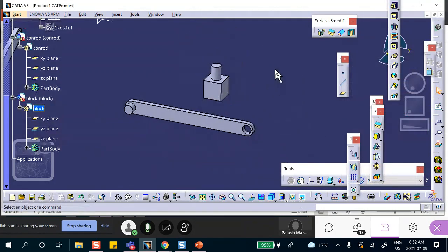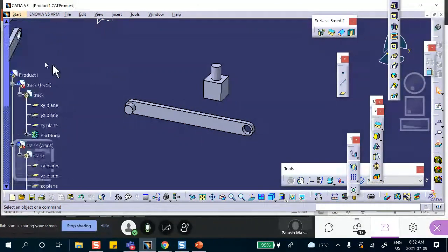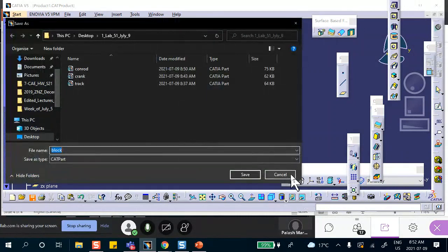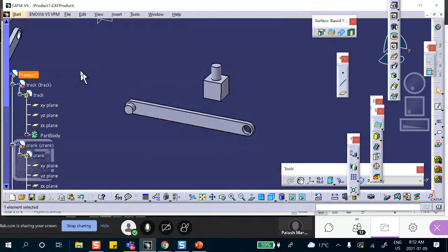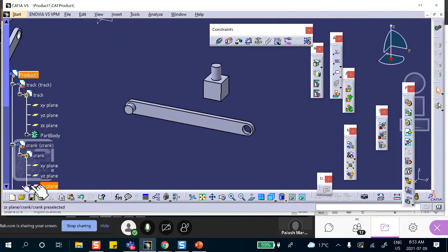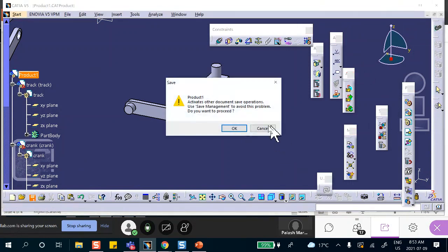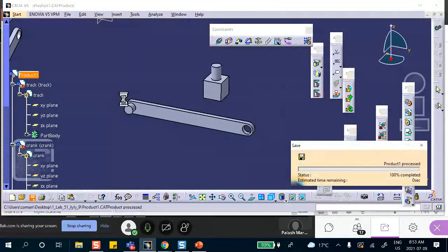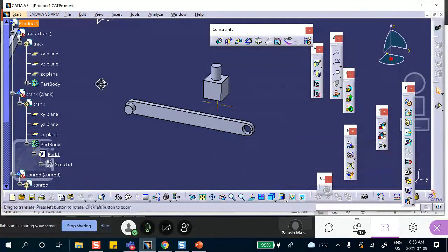Do it any way you want, okay? We don't care. So let's go here, save it. Oh, no, go all the way to the top. This is selected, but I'm not there, see? I'm still in part design. Double click on it so that you go in the assembly design and then you click on the floppy. Okay.